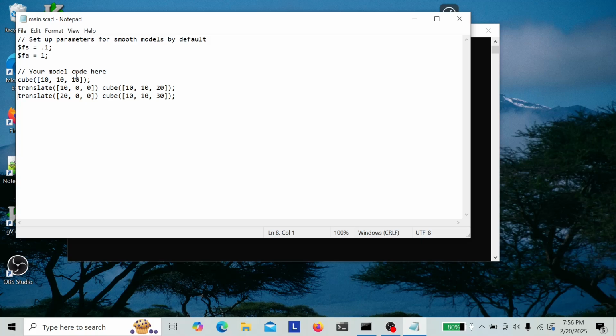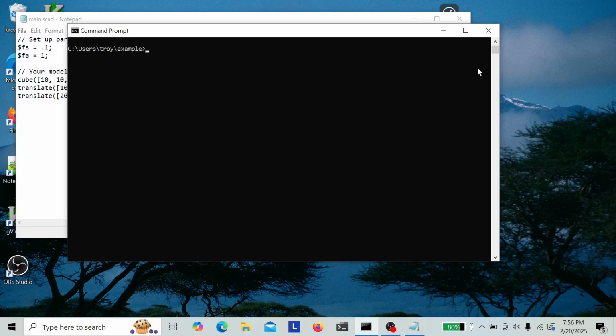So obviously, if you had this on your own machine, you could explore it line by line. Let's go to View, pick Command Prompt, Terminal, and back into /users/troy/example creator, and we're going to do a 3DM build info. So 3DM doesn't automatically rebuild your model because sometimes building a model can take a while. So if we want info on the new version of the model, we have to also build it.